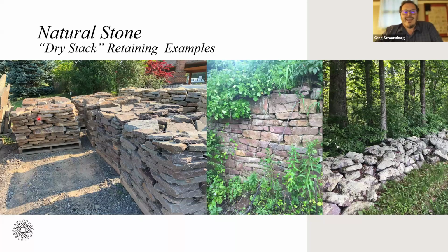No, I can't. And a lot of times what you'll find is that a good dry stone mason will know that first off, but then they'll also start to take that material and lay a little bit deeper backfill in spaces so they can fill up as they go and not have to haul a lot of material out. Helps to sometimes build a double wall. If you know you've got an area on the base, you could build a little bit of a double wall, fill that void, and then you can continue to build up and use the best pieces for the facing pieces as well.